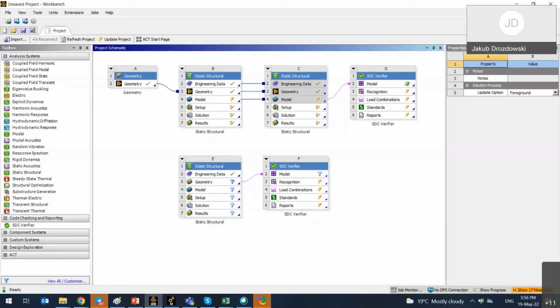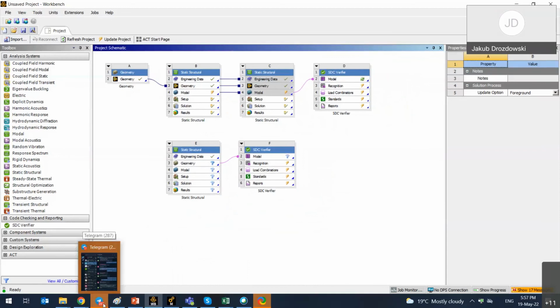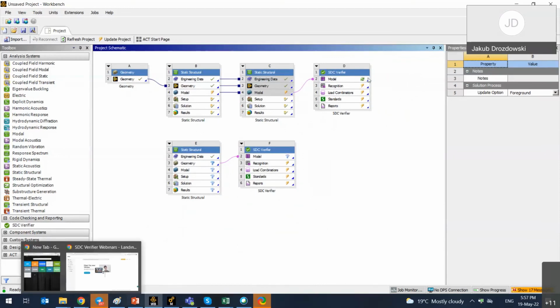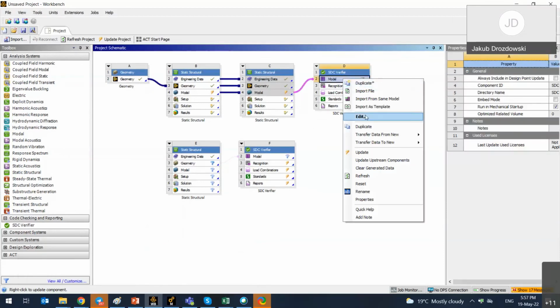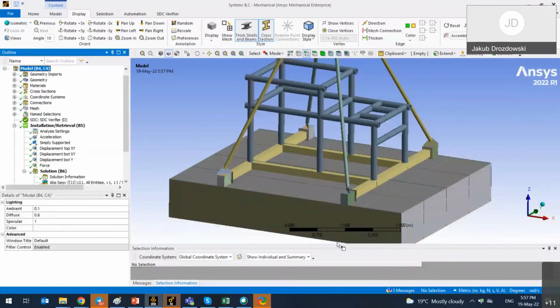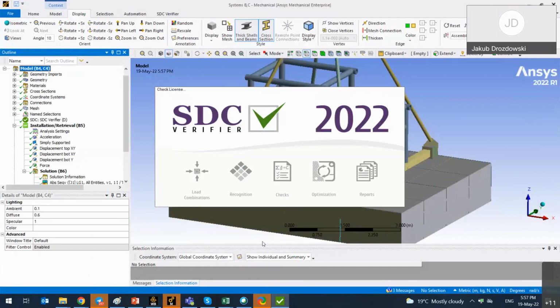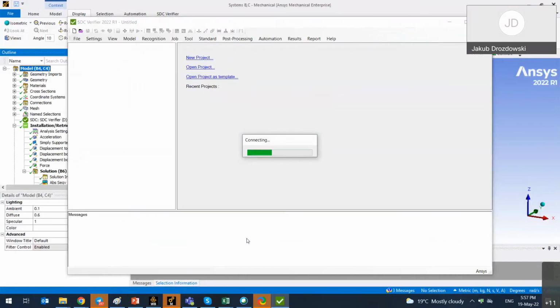I would like to ask regarding buckling analysis in SDC Verifier. How exactly does it choose the buckling length factor of beam elements? In analyzing a complex beam system, the most difficult task is to properly choose the correct buckling length factor, which is really case dependent and depends on the stiffness of the connection and the adjoining elements. So how is it solved? I saw that it recognizes beam elements, but not every beam element has the same buckling length factor.